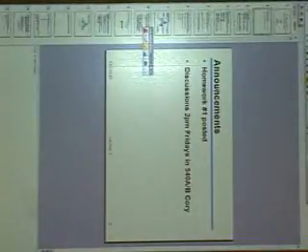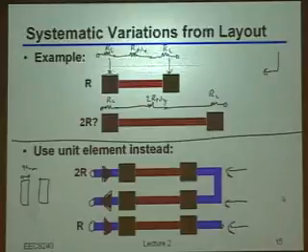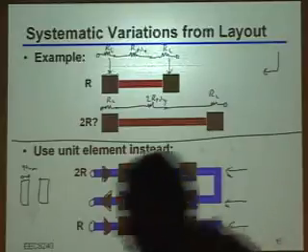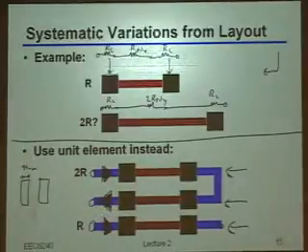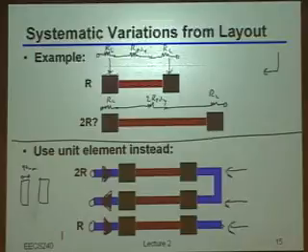We were talking last time about passives, and I think we ended up getting into some of the more detailed layout issues with resistors. As you remember, we spent some time talking about why, with resistors, or more generally with any sort of analog layout, when you want to ensure matching, you really have to follow a so-called unit element-based approach, where pretty much literally any two things that you want to match have to be laid out absolutely exactly the same.